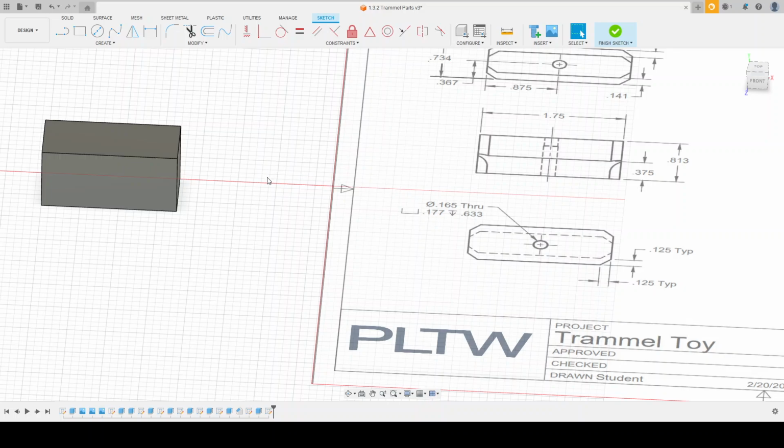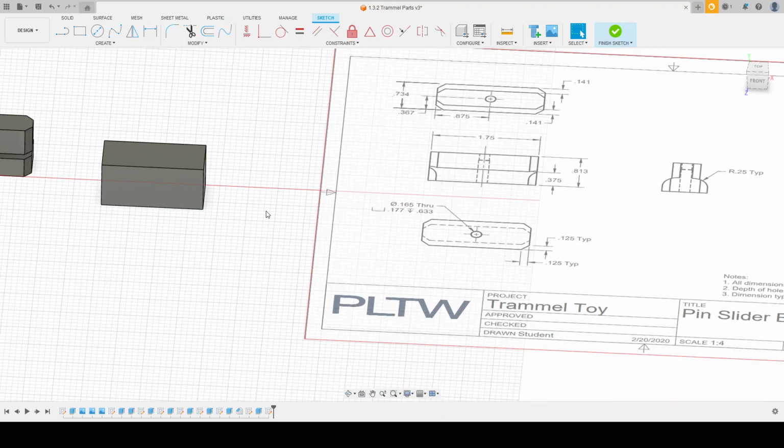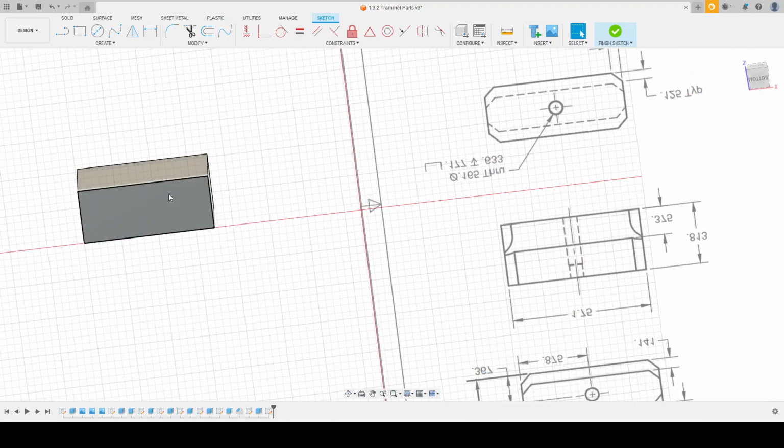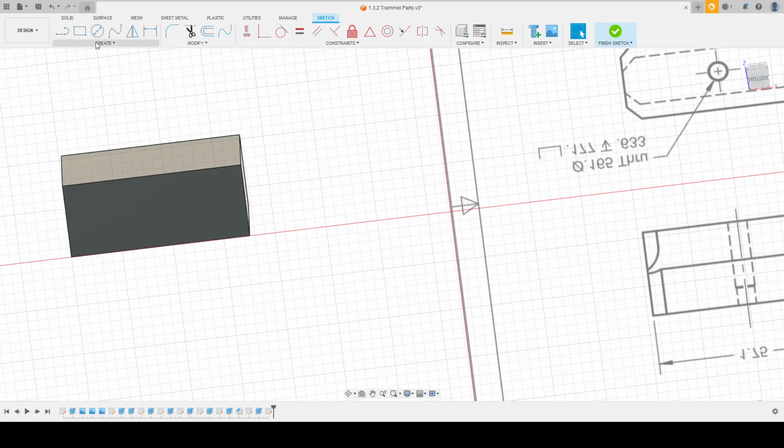But there's another way we can make that happen as well, similar to the commands we saw in our practice on Monday. So let's create a line, a construction line. We want to go from the midpoint to the midpoint and midpoint to midpoint. So now we have an intersection that's the exact center.